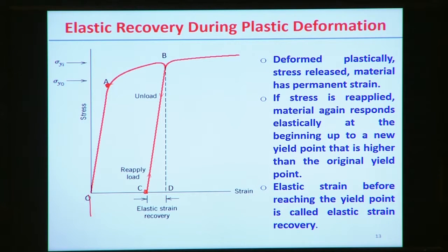So at point C, if we see from the diagram, there is some existence of a permanent amount of strain. That amount of plastic deformation actually exists within the sample, that is not recoverable, since it crosses the plastic limit and enters the plastic deformation zone.